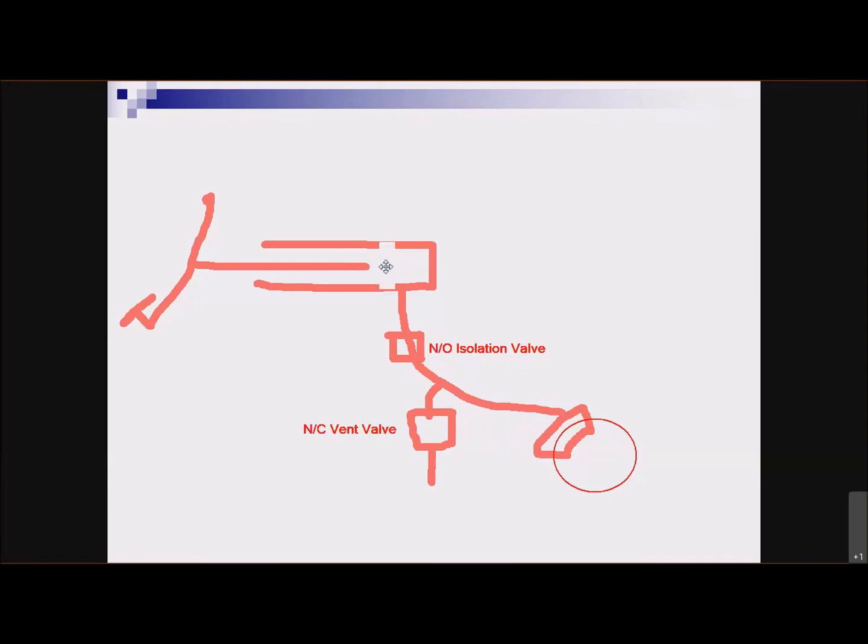That's normally not much of a problem in a short ABS event because there's plenty of travel. But if we have a long event where this vent valve has opened a lot and dumped a lot of fluid out of the system, not out of the system, but just back into another place in the HCU, then something has to fix that brake pedal dropping closer and closer to the floor.